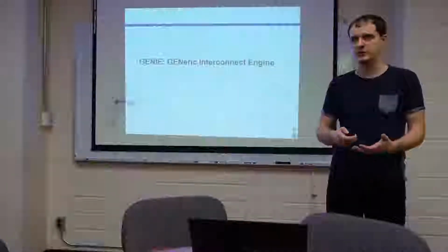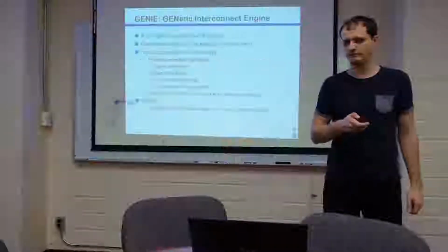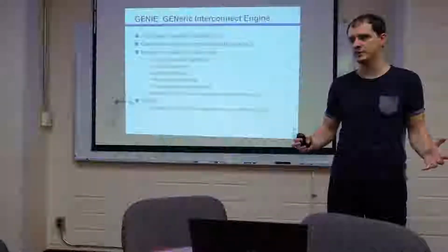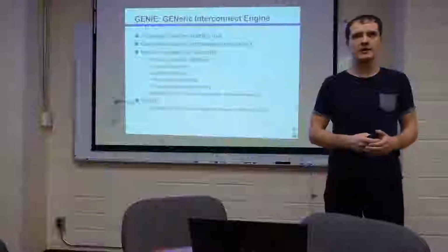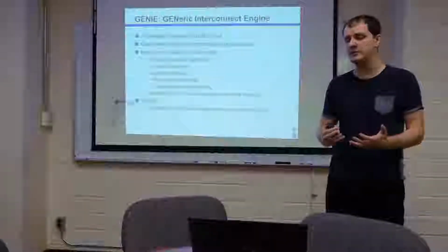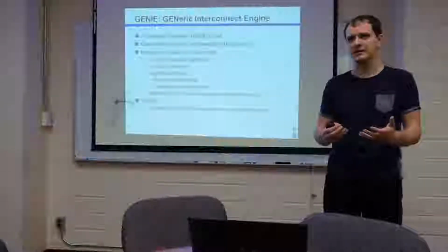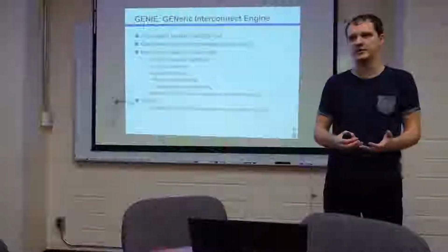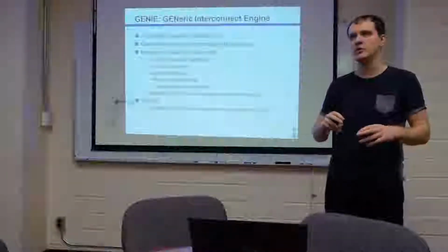So now I'll talk about a tool. It's called Genie, the generic interconnect engine. Like the tools I've been talking about, it's a complete end-to-end system building tool. It will create a system with your functional modules and the interconnect that it generates. And it aims to generate fast and lightweight interconnect, which will make it more usable in situations where previously a tool like QSys would create too much area overhead to be usable. It's what I call the fine-grained world as opposed to the coarse-grained world.